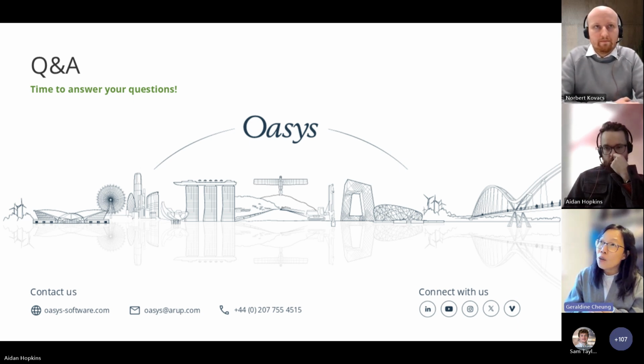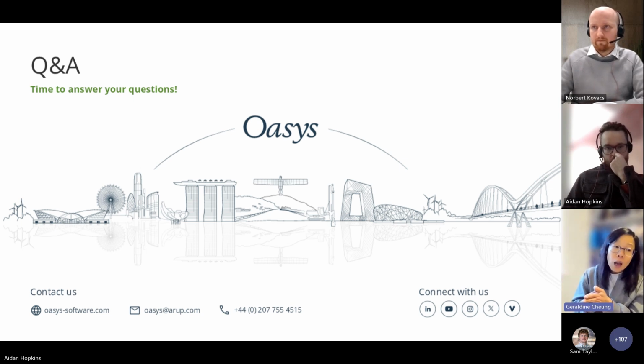But I share your view about getting ground movement curves from different FE analyses and how that interface works, because we spent quite a lot of time on that when we built up our model. That's where the engineer needs to come in, to see how some of these movements can be smoothed as you go from one design section to the next, because we know that ground does not discontinue on plan like that.